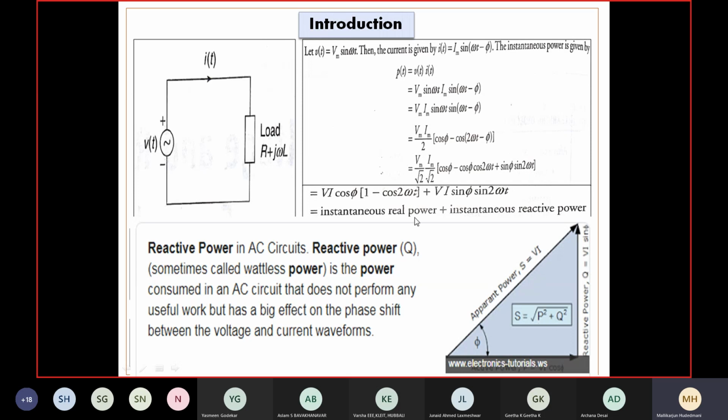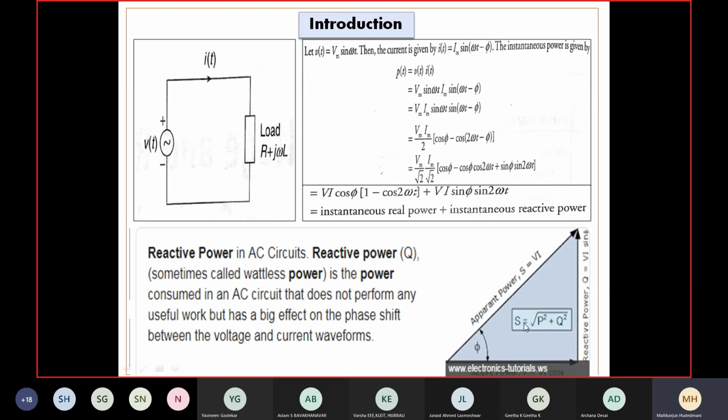So if I find a capacitive circuit, definitely this vertical side, which we have shown as the reactive power, goes downward. It doesn't matter for our relationships of the triangle. Hypotenuse remains hypotenuse, adjacent side remains adjacent side, and the side opposite to the angle remains the opposite side, but reactive is negative, which is going downward. So this is where we get this kind of representation. It is being revisited for our recall.